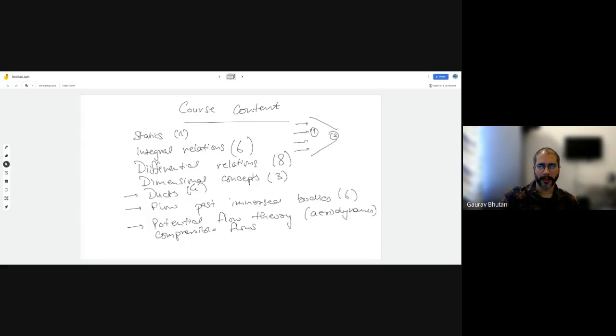But if you go beyond the speed of sound, the idea flips. So if you decrease the area, the velocity decreases. Okay, if the velocity everywhere here is greater than speed of sound. Now this may be extremely non-intuitive, but our intuition is nothing but a function of our experiences. So these kind of ideas are what you will learn in the section on compressible flows. Okay, so 5 lectures on this, and then we'll spend just one lecture each on talking about open channel flows.